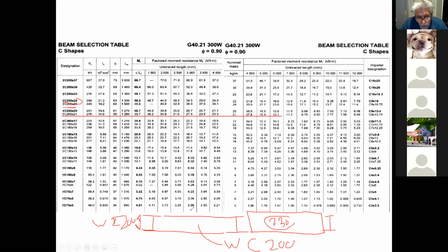And of course, you talk to the architect, and if the architect likes to create this gap between the columns so that people can pass wires or pipes or whatever, then this would be another choice. So it all depends. This is something you would coordinate with the architect. Does he mind losing this extra 30 millimeters inside his building? Or does he want to keep the thickness of the wall down to 8 inches? It's up to, you know, this is things that you discuss with him.